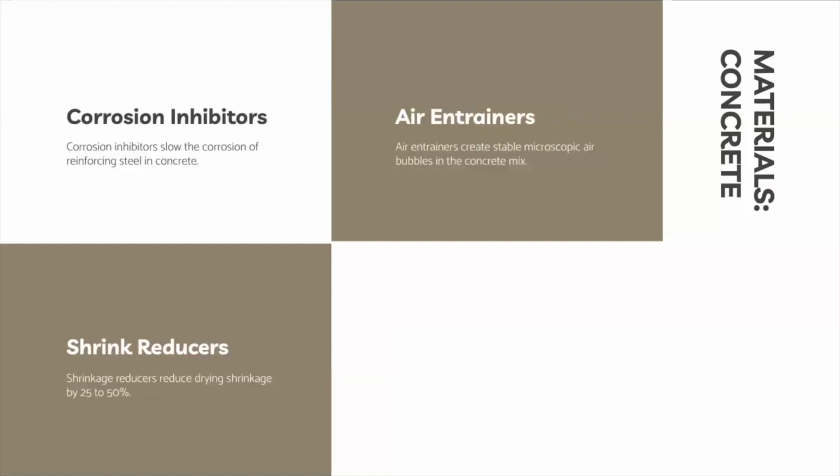Corrosion inhibitors are vital for slowing the corrosion of reinforcing steel in concrete, particularly in structures exposed to high chloride concentrations like marine facilities, bridges, and parking garages. While beneficial for corrosion protection, some inhibitors may also impact concrete setting, air content, and shrinkage cracking.